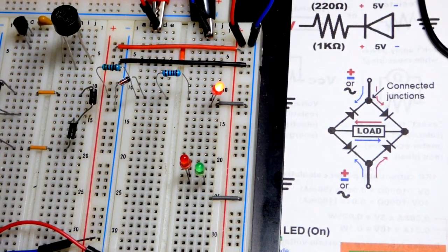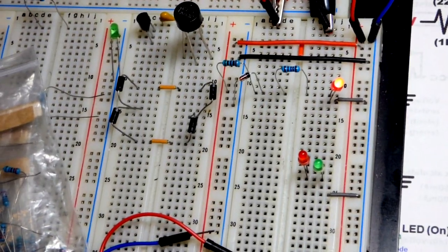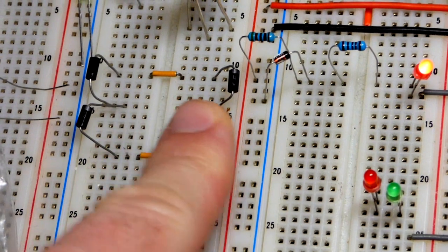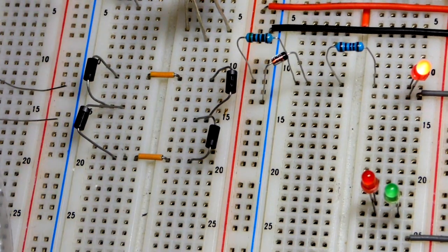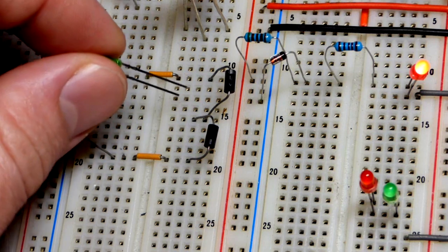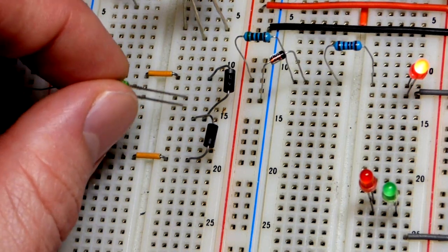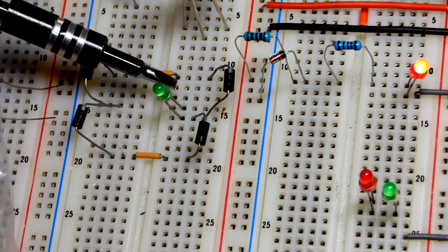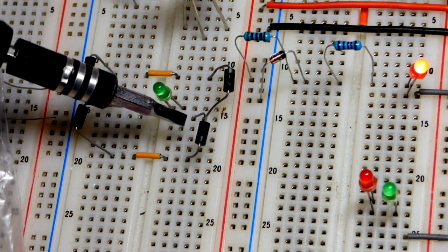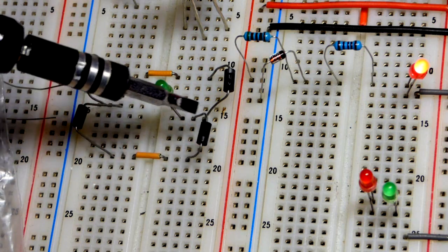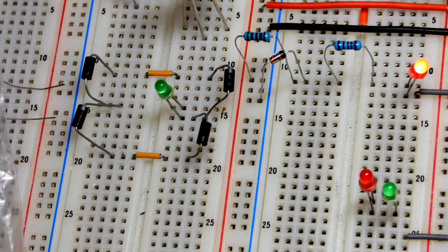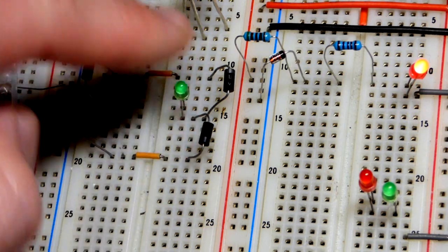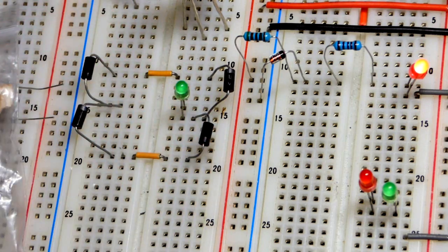But the main takeaway is, now we will attach the load. So I'm going to grab the LED first. And so again, the LED is a diode, just like these diodes. The anode is the long lead, the cathode is the short lead. And so we can run positive here through the LED towards negative that way. And then same with these. We can go either way, as long as one side or the other is more negative. So we have a flow either that way or that way.